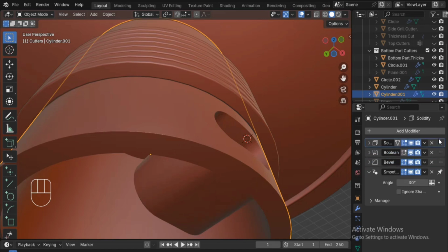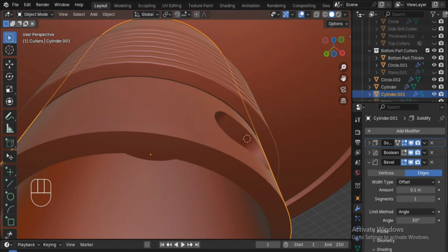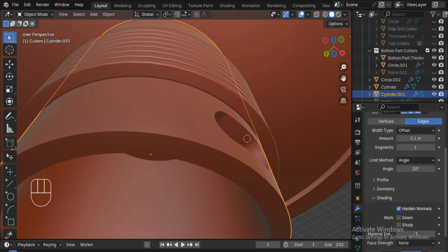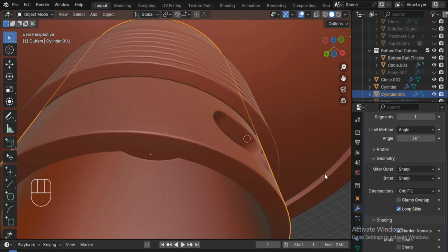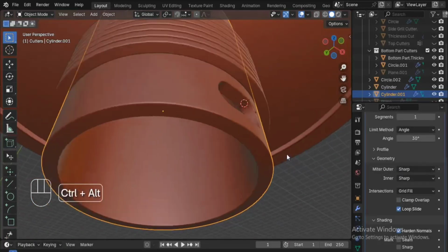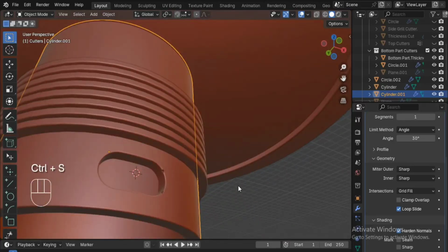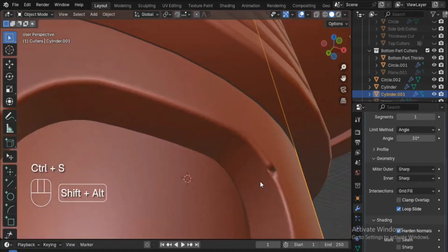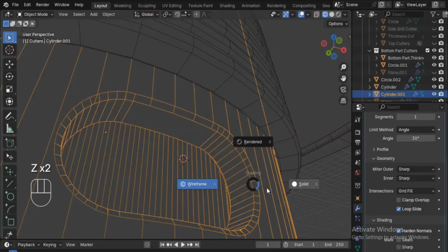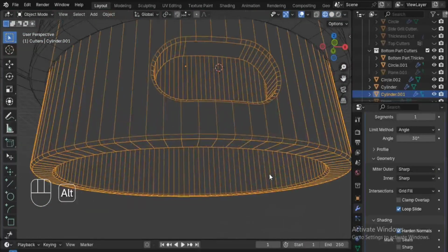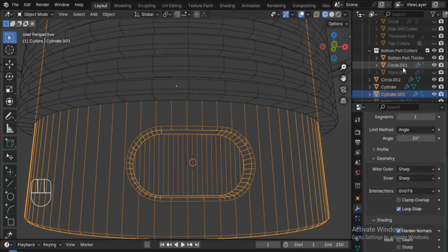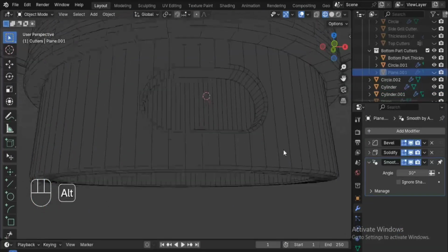I just didn't check the fast option. Sometimes checking between the exact and the fast option makes the difference in the cutting. Sometimes the distortion goes away with the fast, sometimes the distortion happens due to the fast, and this kind of thing happens. So you need to check with which method the object is properly able to cut the other, which algorithm is just more preferable for the shape you're trying to cut into.